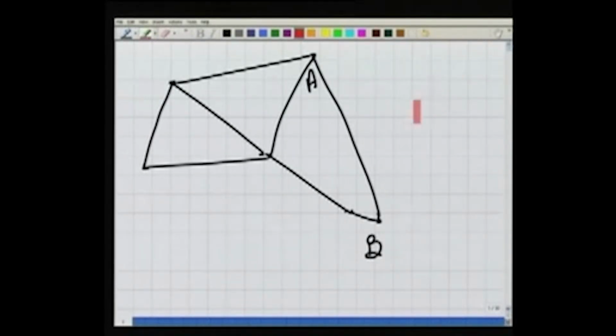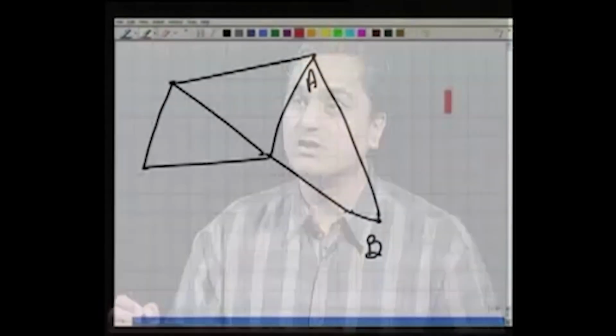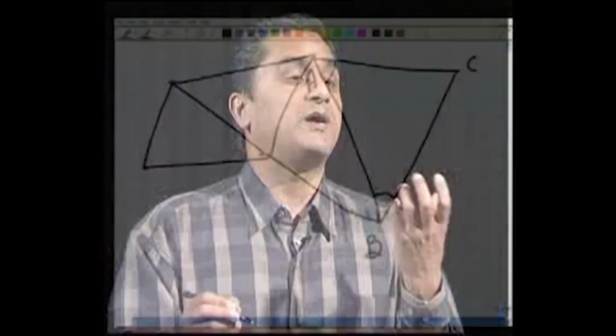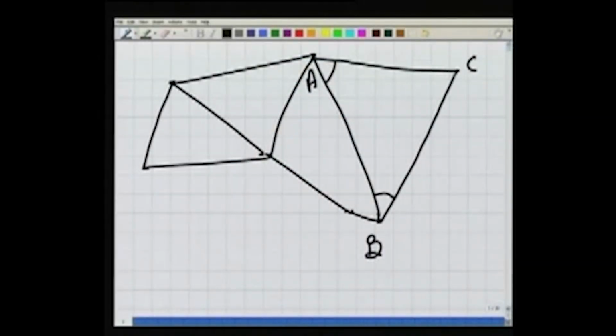Over here, our station, the actual station where we can put our instrument, is not visible, or maybe something else is more visible, or we want to take that as a station. This is the more important point. We want to take something here, let's say C, as our station, and we bisect that C so that we can also measure our angles at B and A. We prefer to bisect this C because it forms triangle ABC as a well conditioned triangle.